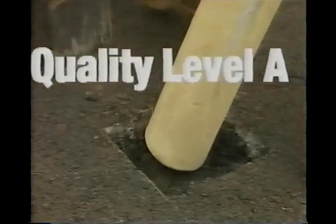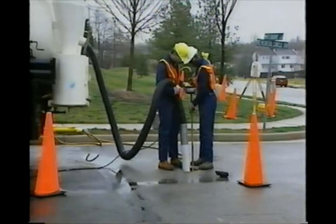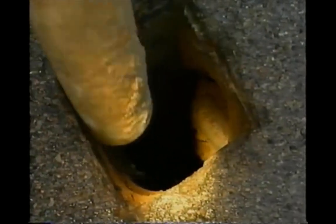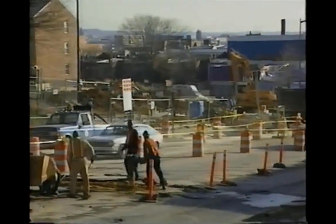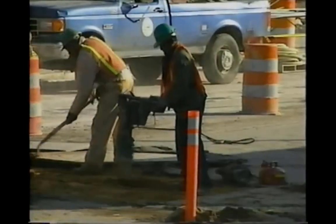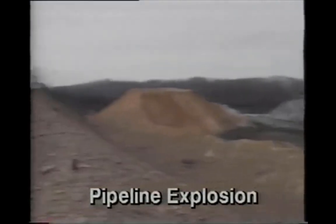Quality level A information is the highest level of accuracy currently available. It involves adding locating to the quality level B information. Locating is the exposing of buried utilities. How a state or municipal public works agency engages a subsurface utility engineer may be as important as whether they engage one at all. Why? Because inaccurate subsurface utility data is probably more dangerous and inefficient than none at all.